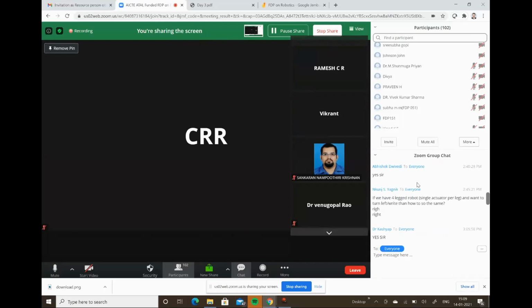I hope that in yesterday's class, we had the session from Inga Robotics on kinematics and dynamics of industrial robots. Those concepts should be applied when we go for legged robots, and in that case you should consider the gravitational force, centrifugal forces and other things. All those nonlinear effects should be considered for controlling the movement of legged robots. In wheeled robots, we need not go for that.